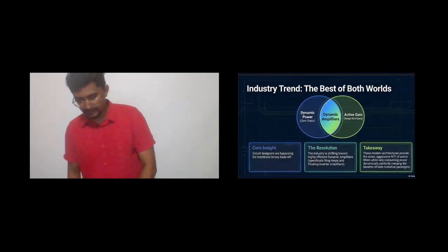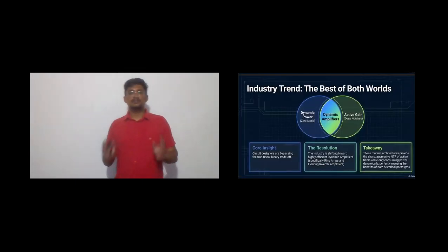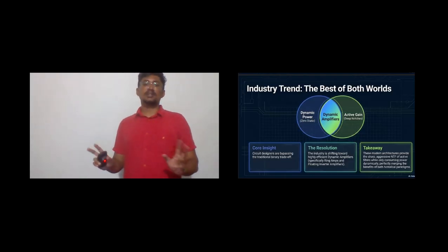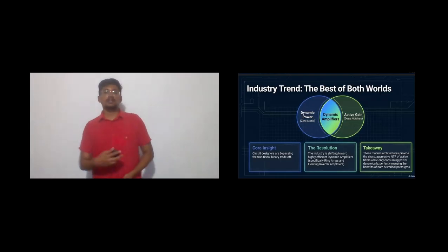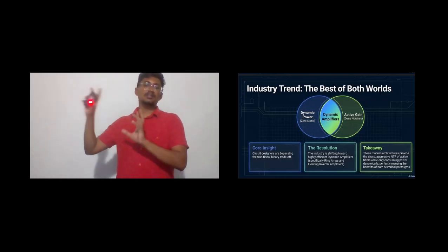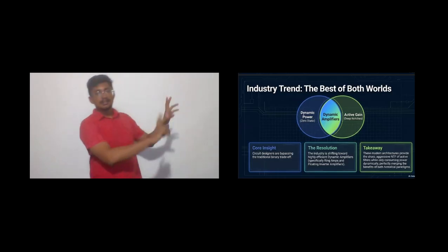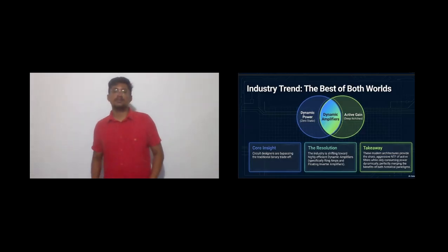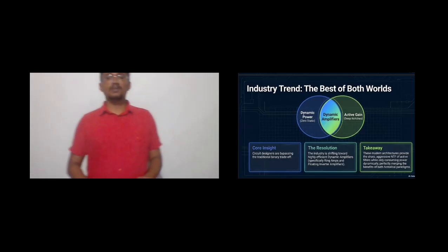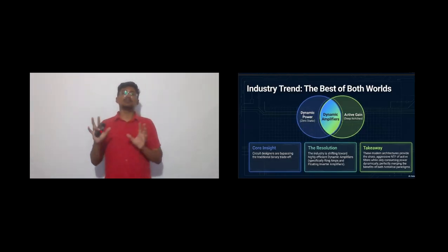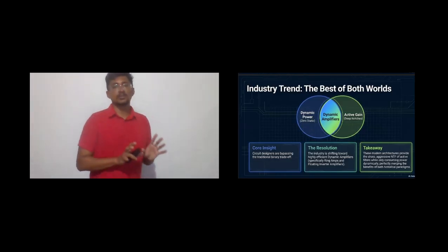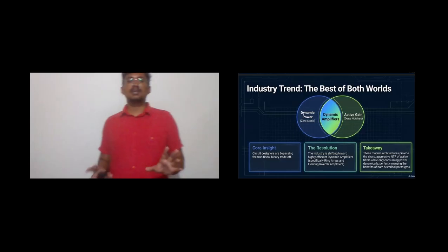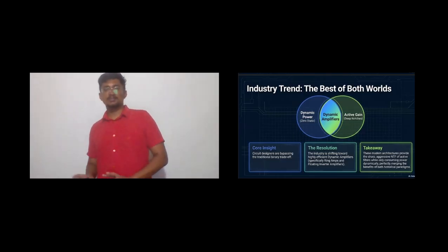So to wrap up, it is worth looking at where modern industry research is heading. Designers today are fighting to get the best of both worlds. The current trend is to replace those power-hungry continuous time OTAs with highly efficient dynamic amplifiers, especially ring amplifiers or floating inverting amplifiers. These structures provide the high active gain needed for deep noise suppression, but they only draw current during clock transitions. Essentially, they deliver active level performance at near passive power efficiency.